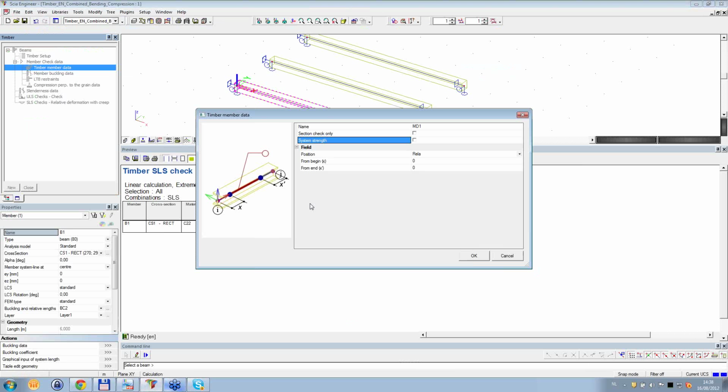So in this case, if I would imagine that this is a floor system with 3 floor beams, they are connected by some kind of plate, for example, I could take into account an additional system strength of, for example, 1.1. So this means I get a 10% strength increase, which is quite significant. Now if you start adding this with the KH depth factor that we've seen before of 1.3, you get quite a significant strength increase using these coefficients.